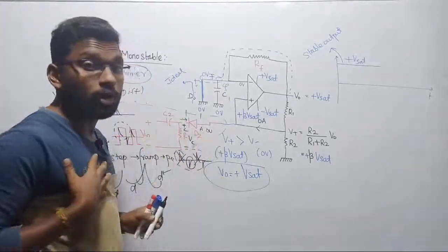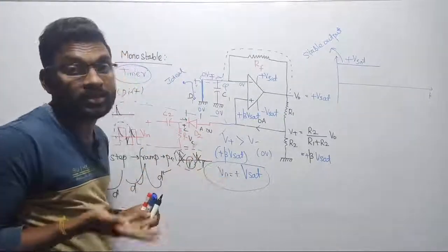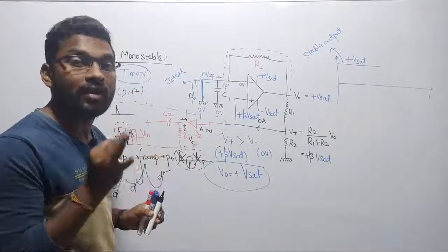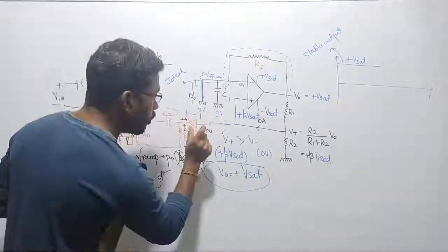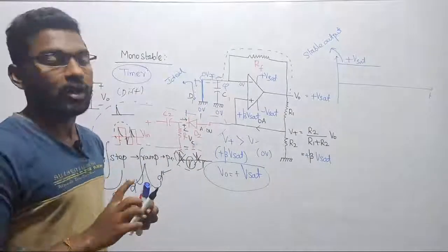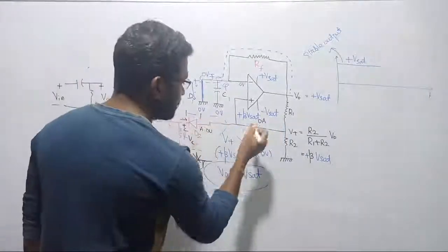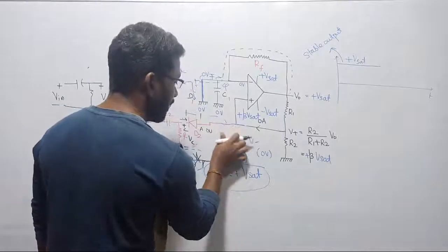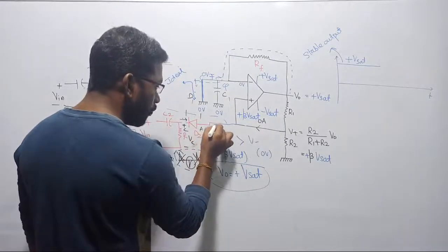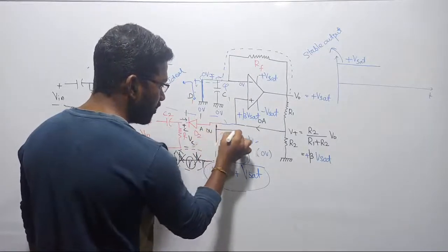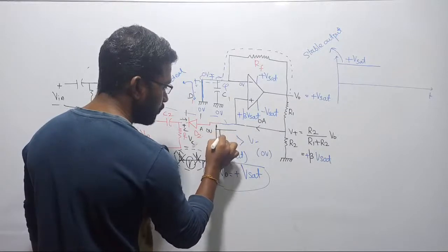Across the anode I have 0 voltage, but across the cathode I am injecting negative voltage, sir. A negative potential value is always less than 0, sir. So the anode voltage is greater than the cathode voltage. The diode will turn on and it will allow these negative spikes to the oscillator, right? So at this point, the output of the diode is going to be a negative spike.